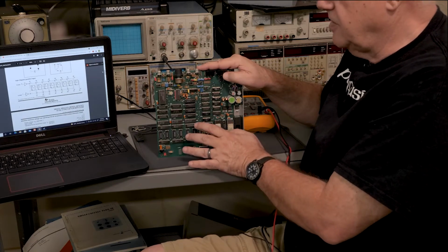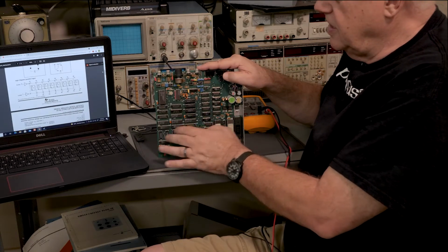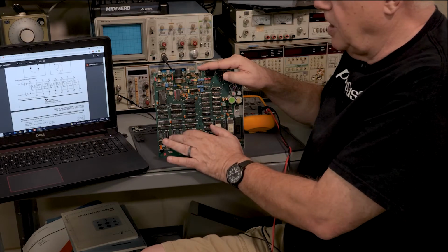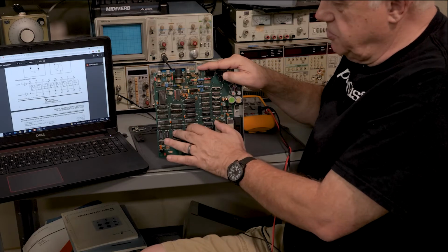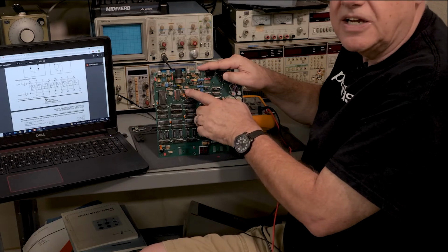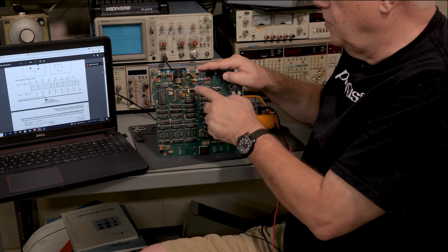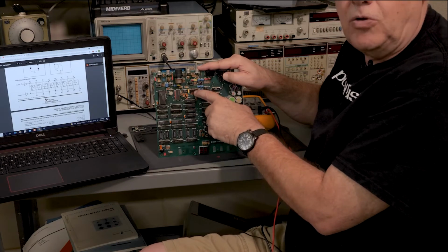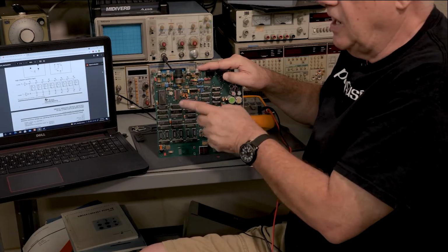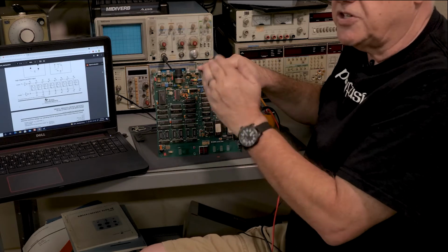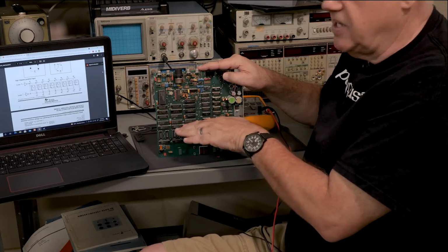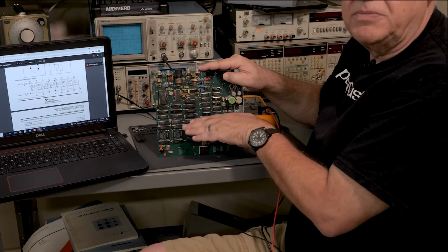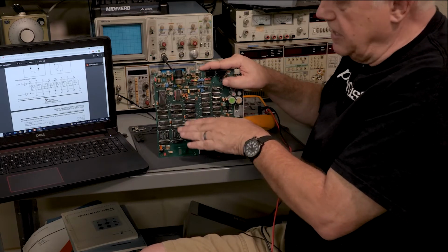So what can it do with multiple bits in the opcode? It can do things like, well, it's this instruction, but also while it's doing this particular function, I want you to switch the A to D converter to a D to A converter. I want to set the sample and hold for the left input because I want settling time, so the next instruction, which is read the left input, is going to have time to settle while I'm 1 instruction behind. That's called pipelining, okay?